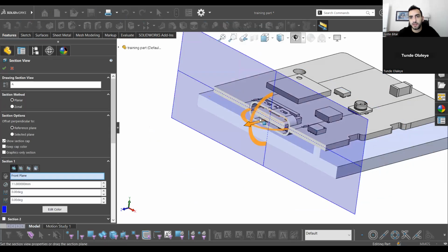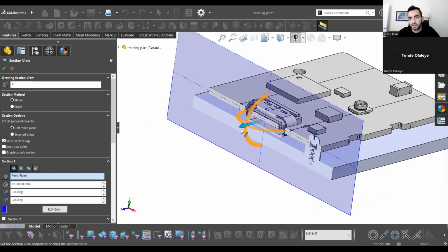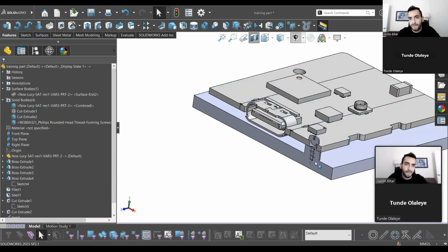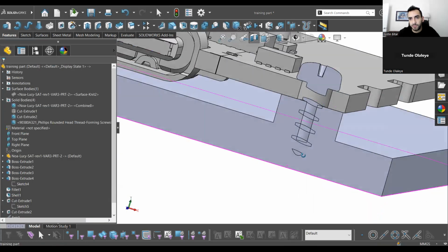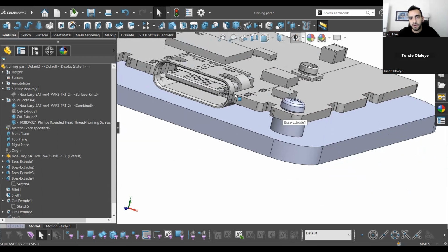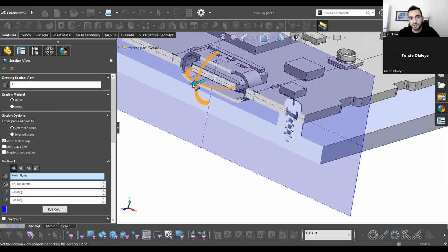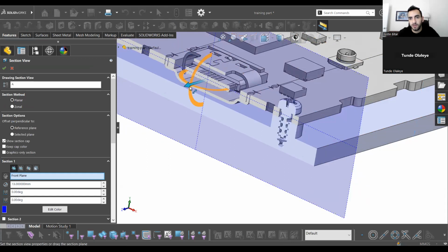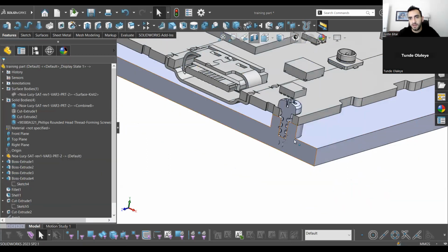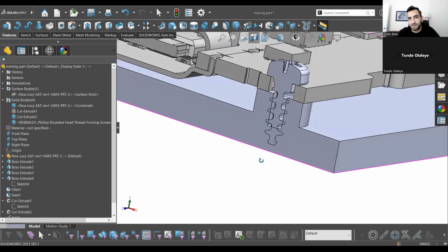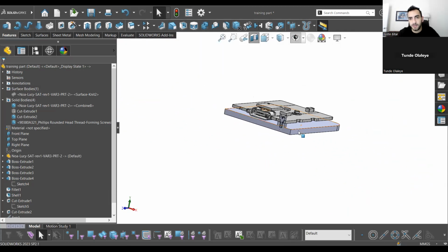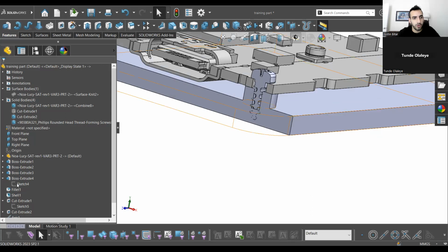And let's just double check that our hole is deep enough. So I'll just take a cross section plane and I'll move it into the part and I'll see, okay, yeah, we're not actually quite that deep. So this screw actually wouldn't really work here. So let's just, I mean, we've already kind of minimized everything. Let's just make this hole go all the way through.